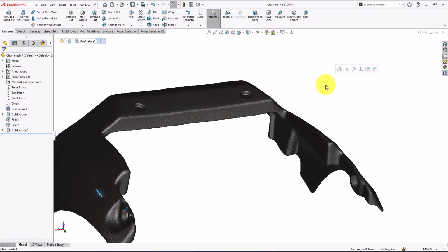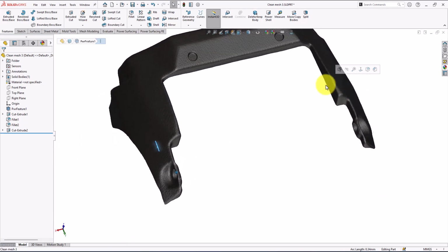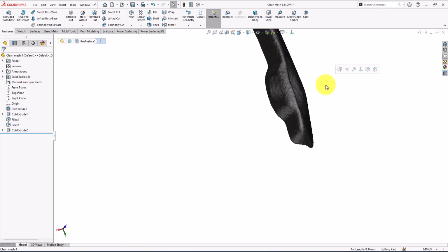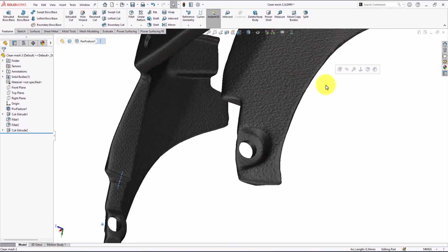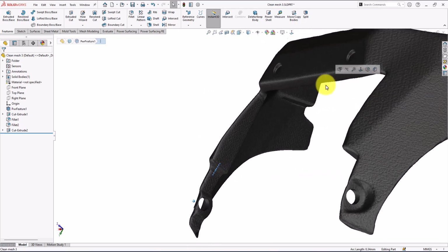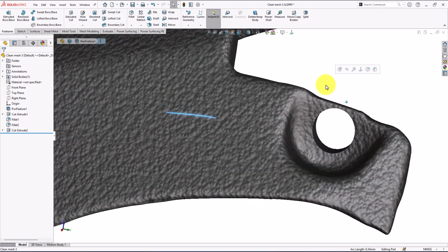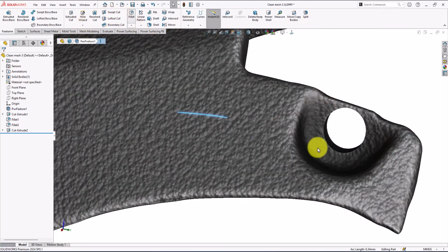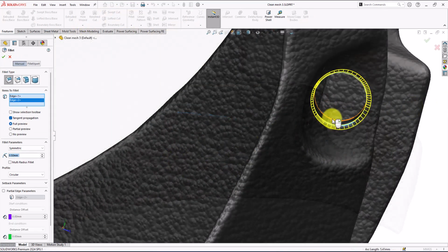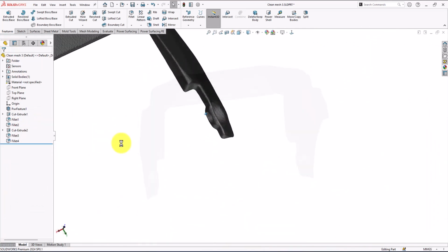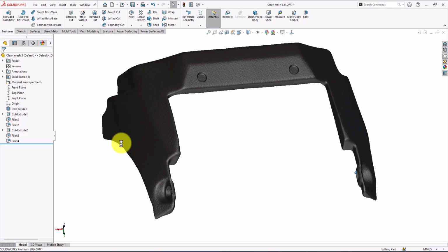And that's, I think, the concept of reverse engineering. That was too thin for the cut extrude, and I went and made it thicker, so that's maybe better than before. And I can also make a small fillet or radius here. Okay, that's great.